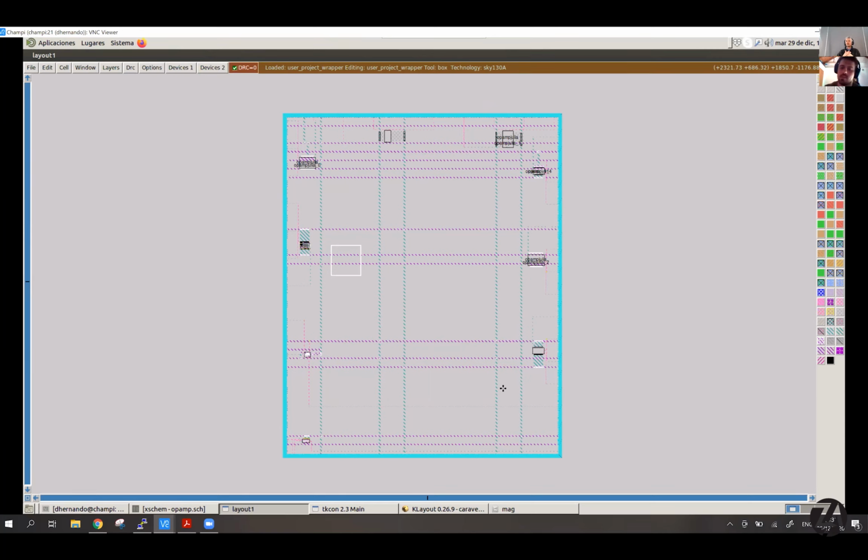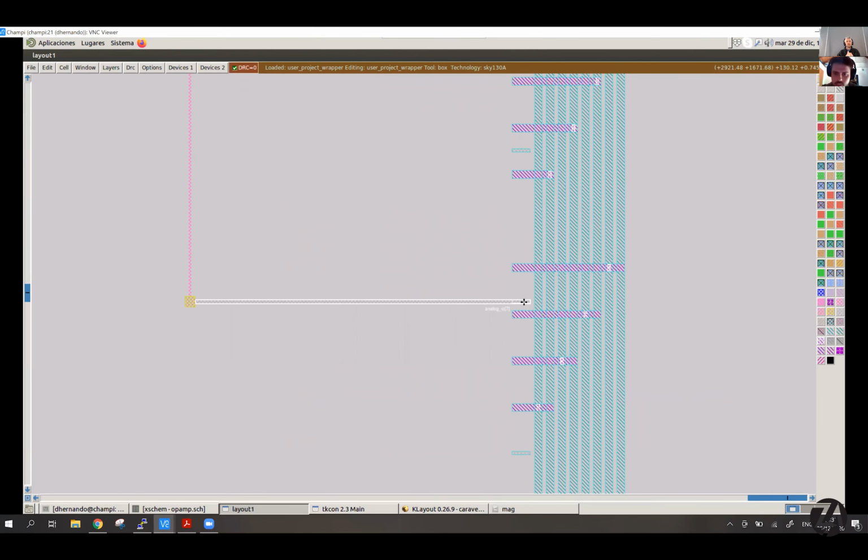Yeah, but the ones that you get exposed are, yeah. I mean, yes, I have. If you see here, I connected to the analog pin in the wrapper, but this analog pin is connected to a path with an ESD. It has a big impedance, and there is also a pin available that has no impedance, and we wanted to use that one. Okay. That's the routing we did.